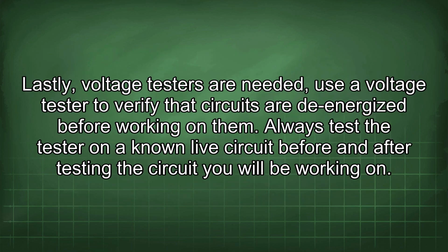Lastly, voltage testers are needed. Use a voltage tester to verify that circuits are de-energized before working on them. Always test the tester on a known live circuit before and after testing the circuit you will be working on.